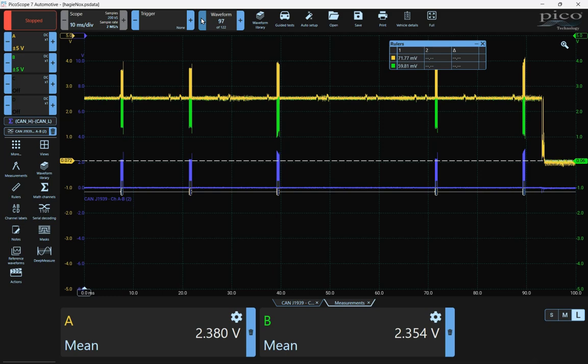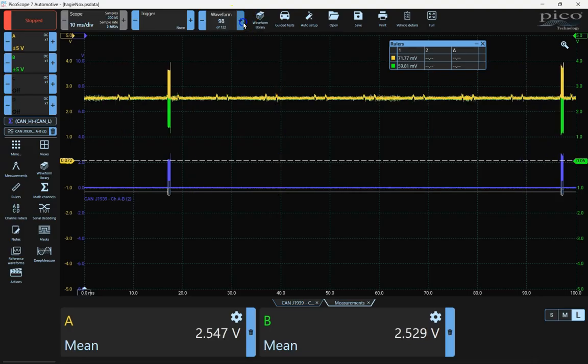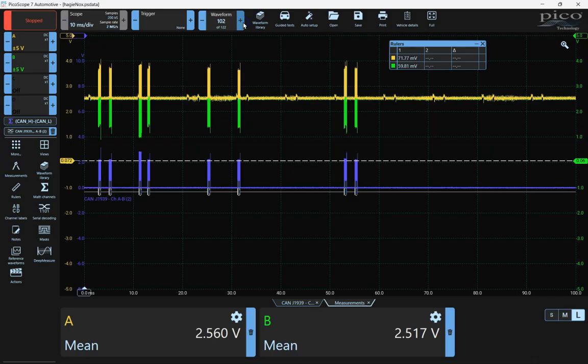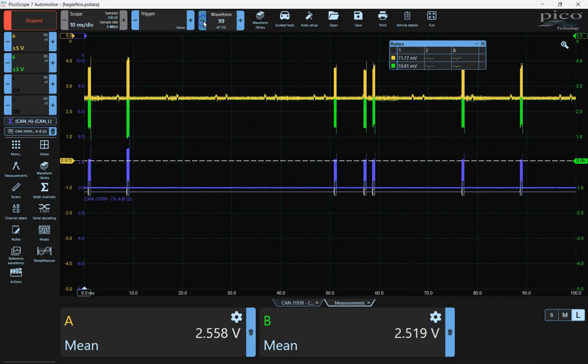It was one of those things where we could wiggle the wire harness around. The duration of the short probably wasn't long enough to set the DTCs. So unless you're watching with a very fast multimeter with peak hold, looking for a problem with the wire harness, and you wouldn't expect that because nowhere was this anywhere near ground. It was actually a section where it was free and not connected to anything.